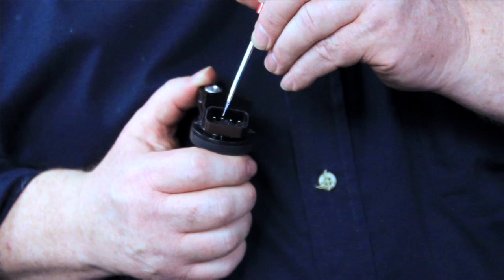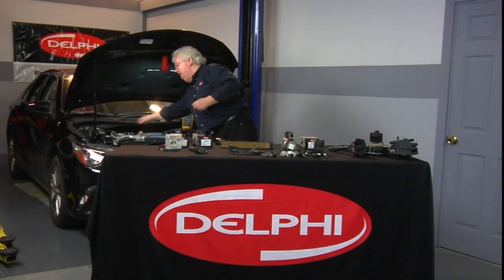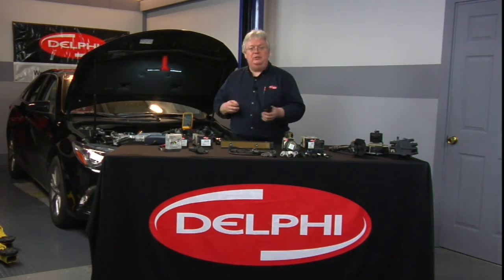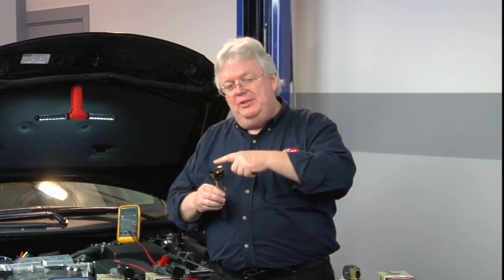And then we have a trigger signal from the PCM every time we want cylinder number 2 to fire. We're going to turn on a transistor. It's going to be a 0.5 volt square wave kind of thing. And then we're also going to have some feedback if the coil actually kicked and did its job. Now, just like the parallel circuit for power to feed this coil is the same circuit as for all 4 coils, that feedback circuit is the same for all 4 coils. We'll just see a different kick for each individual coil when it's its turn to fire. And that's how the PCM makes sure that this thing is indeed producing a spark. It's making some action going on.